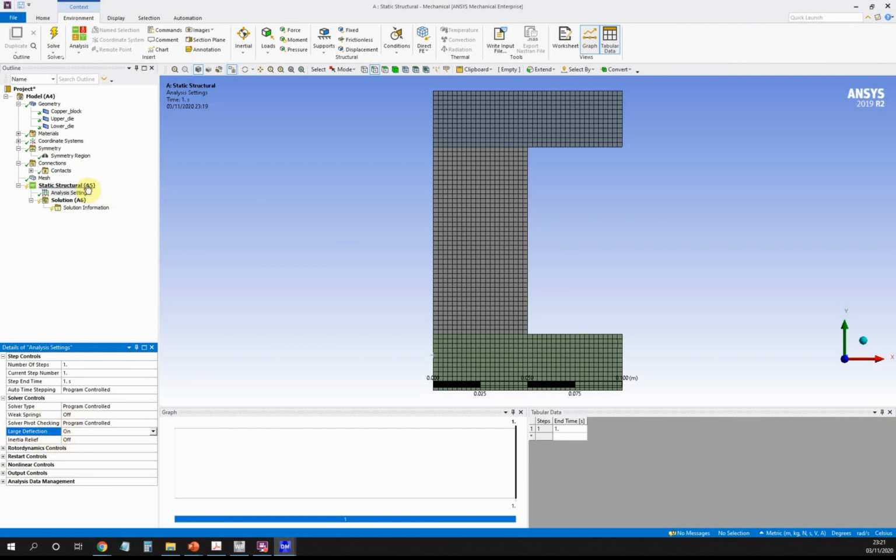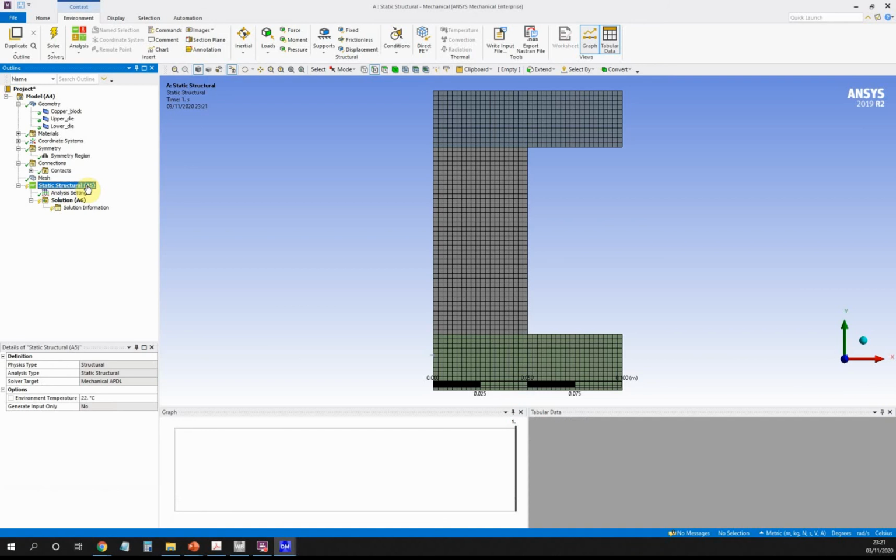Okay, so now we need to put some loads and boundary conditions. As a first step, we're going to apply a displacement to the top die. We're going to move the die down by the amount that we want, and we're going to see what the reaction force as a result of that is, which tells us the force that's required to reduce it by 25%. Later on then we'll go and put in the pressure load and see if they work out.